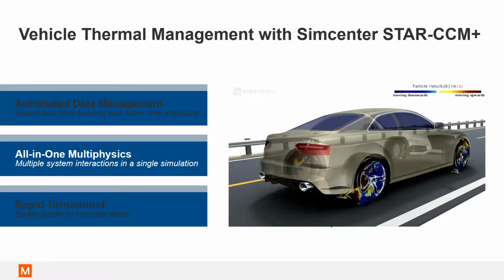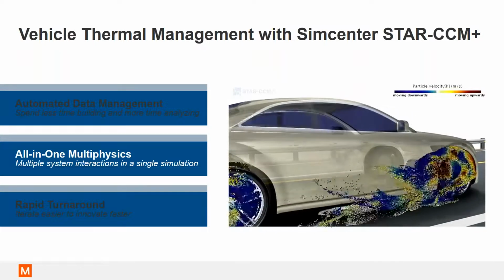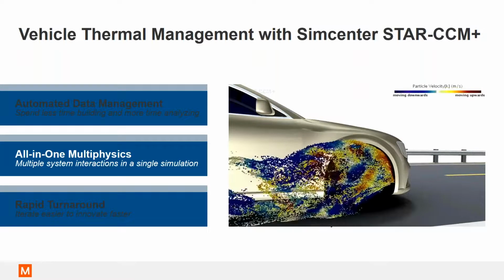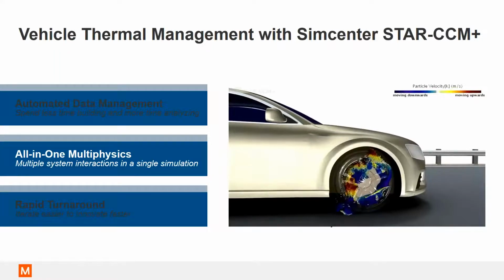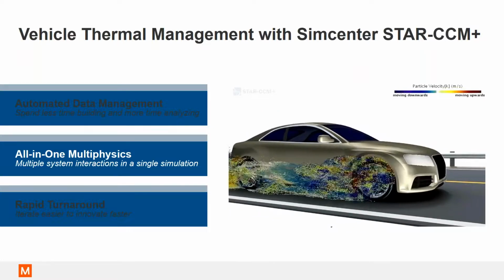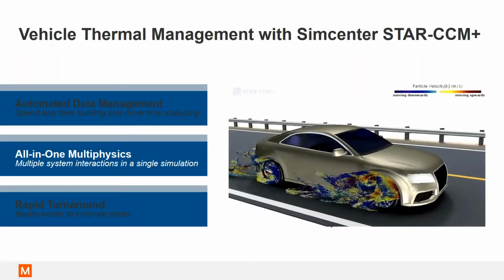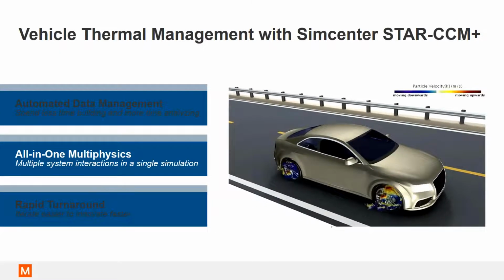To conclude, we have just modeled all of this in a steady state thermal model, but we can go further than this and simulate transient models covering all disciplines and physics. It is possible to enable long thermal drive cycle and soak simulations with a single tool for both thermal and fluid regions. We can also capture harsh driving conditions like wind, snow, or rain because Star CCM Plus can simulate all these multi-physics conditions.